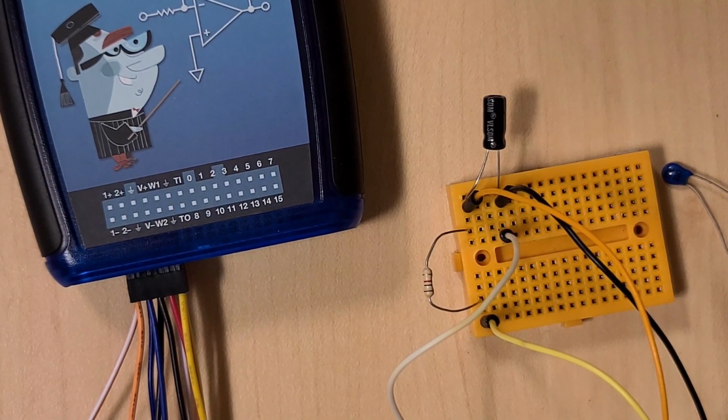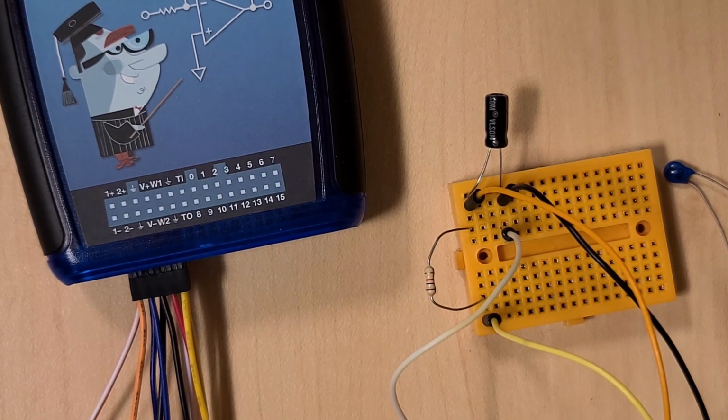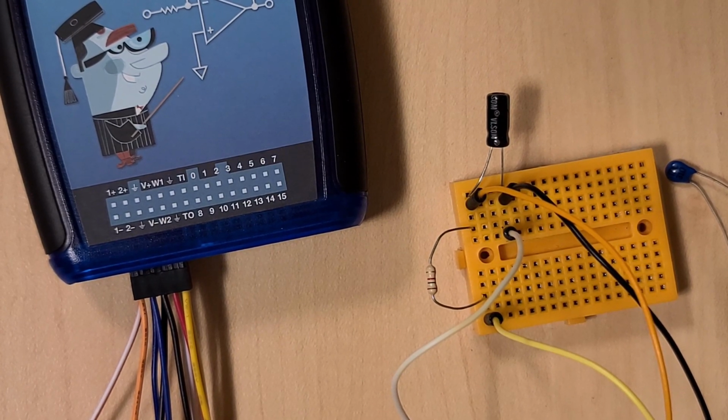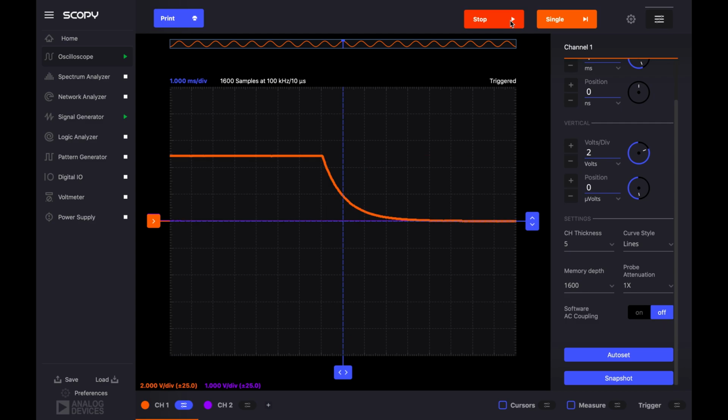Once we're good with that, we're ready to turn on our scope. So let's see what happens. I hit run, and we get an exciting looking waveform here. So what's going on? If you see something weird like this happening, you can do a couple things. You can just hit stop, and it'll stop data acquisition. You can hit single, and we'll talk about that in a little bit. It basically fills the screen once and says, here are your readings, and that's it.